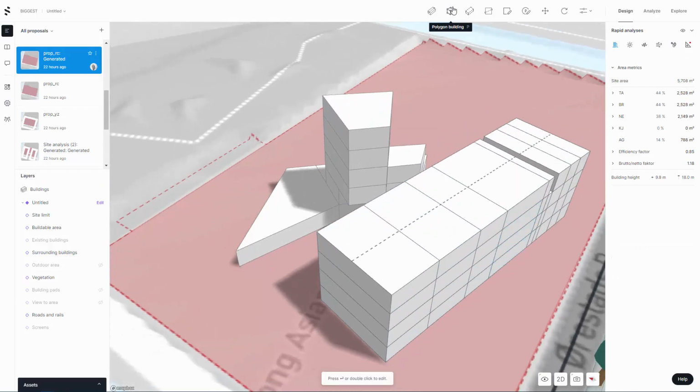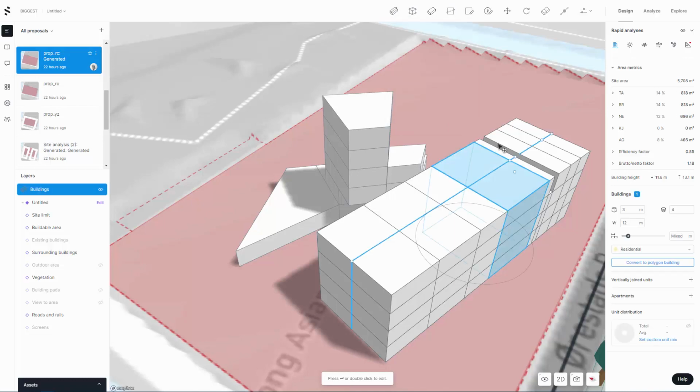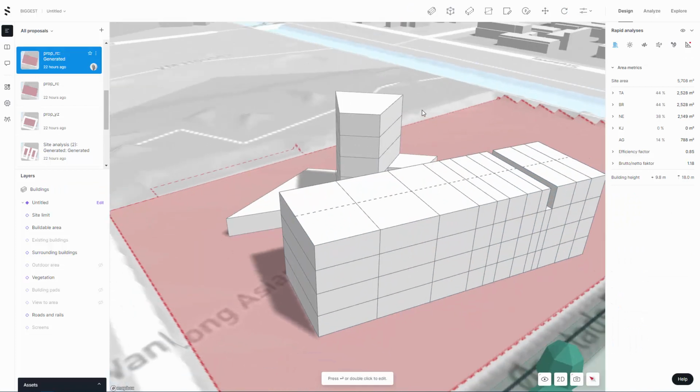And then finally with the line editor building, we can grab those components, split the section, or use this add point tool, which is probably a little bit more interesting to use, but you can start to break up your geometry in a lot more detail.